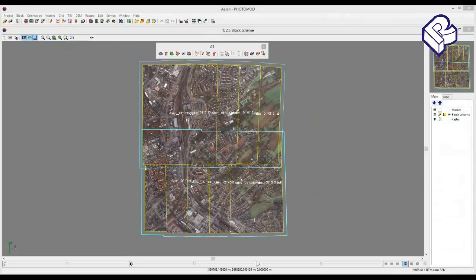If you haven't preliminarily loaded exterior orientation data, GCPs enable us to calculate them for every image. Otherwise, GCPs make them more accurate. When we talk about standard overlapping areas with 60% in strips and 40% between strips, the recommended covering of the block by GCPs is calculated like 1 GCP per 5 bases of the survey.